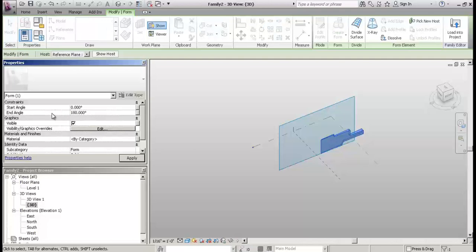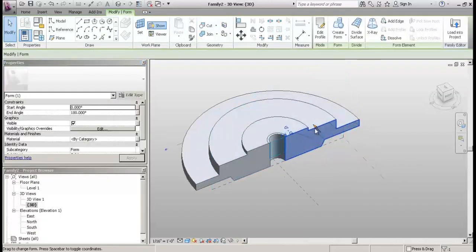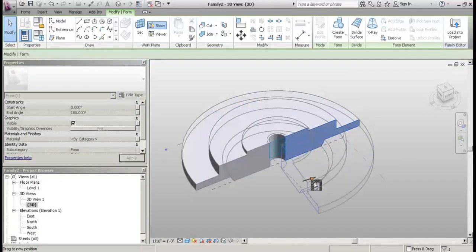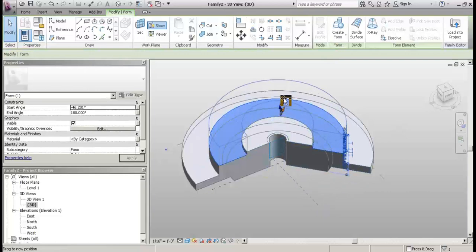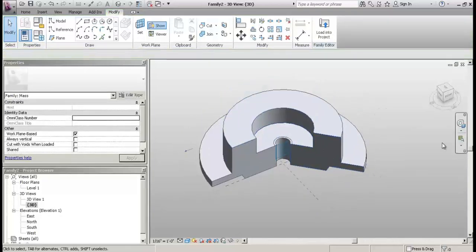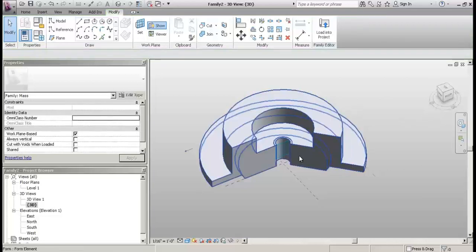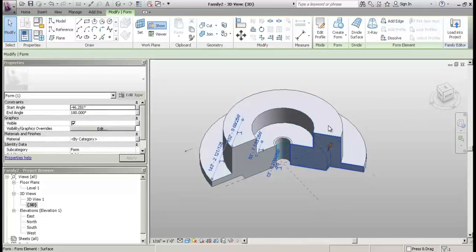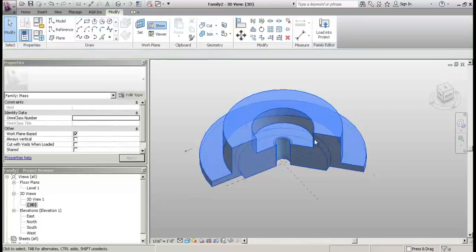Oops, 180 degrees, right? And then if I wanted to actually drag and pull, I have different shape handles now out of that object, and Revit remembers those embedded things you were doing. So in this case I can pull it up or pull it down. So let's go ahead into the editing environment for these conceptual masses. Tab over, select the whole object, delete it off.